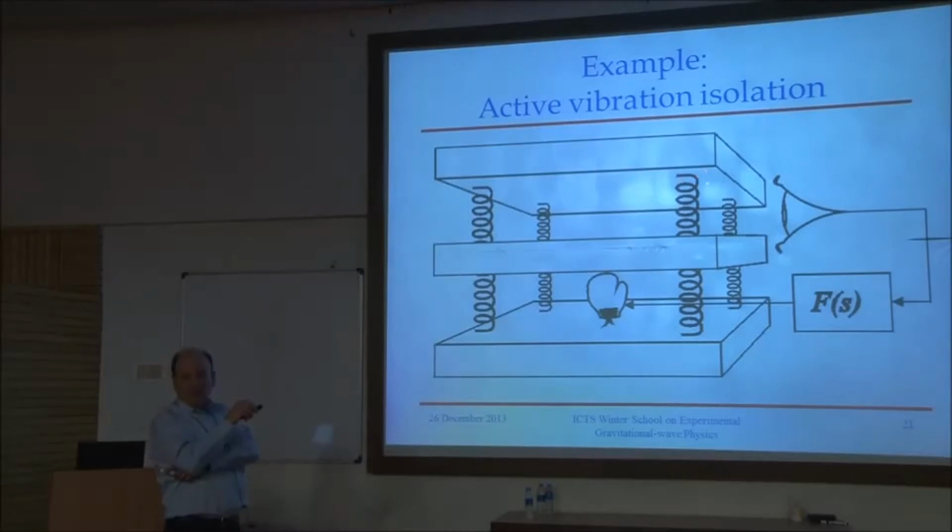I'm going to say that because this platform has mass and it's on a spring, the relative displacement of this mass with respect to this mass functions as a vertical accelerometer. Now, when we actually do this in real life, we put separately engineered accelerometers on rigid platforms for a variety of good reasons. But just for thinking about this in a 1 degree of freedom sense, just the vertical, give me this simplification. Or you could let me say, I've just drawn a vertical seismometer, vertical accelerometer with a really big mass. Either way, it doesn't matter. So I've got a position sensor drawn here that is measuring the separation between these two masses. And it's measuring that because, let's say, this platform was in the process of being accelerated upward.